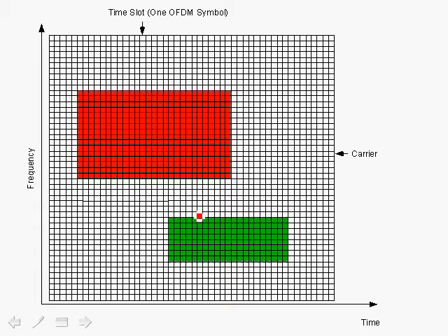Now the reverse is also true. That is, the subscriber stations can also be told in advance which data regions they can use in order to transmit their data to the base station, and the base station will then perform a forward FFT and, knowing which region is allocated to a particular subscriber, decode the data burst from that particular subscriber.